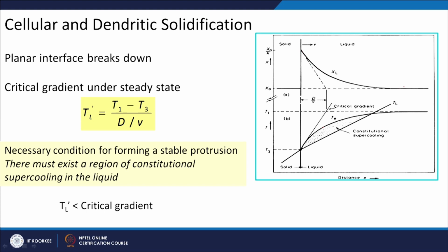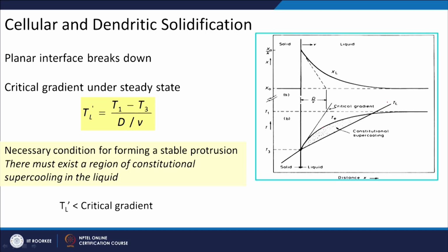Now, when I am taking out the heat from this bar, I am actually superimposing a temperature gradient on that. You can see that there is a temperature gradient given by TL: at the end from where I am taking out heat, the temperature will be lower, and inside the temperature is higher. Now, if that temperature is lower than the melting point here, what I am doing basically is undercooling the alloy. If my imposed temperature is lower than the melting point, that means I am doing an undercooling.